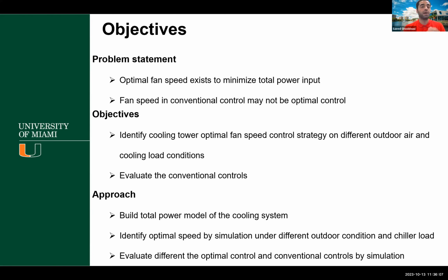To make a long story short, we try to control the fan speed so that our chiller system, which is coupled with the air handling units to provide cold air inside the area, compensates the disturbance. We want to change the fan speed to make this cooling system, including the cooling tower and chiller, work efficiently and at an optimal point, right?